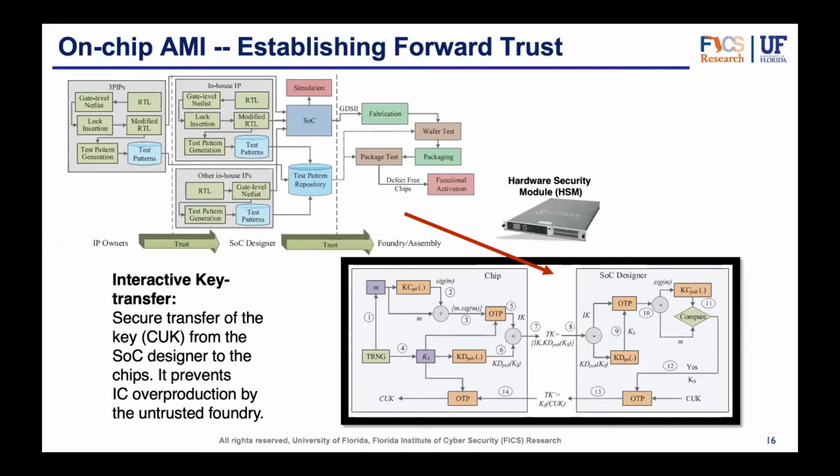Now, the secure channel: basically, we established the direct communication between the chip through a host and AMI, but it could be done using a hardware security module. And we're in discussion with Synopsys to explore both scenarios and see whether we can eliminate some potential man-in-the-middle attack using testers, as Brandon described earlier, by placing, for example, a hardware security module that performs the majority of the communication to AMI.